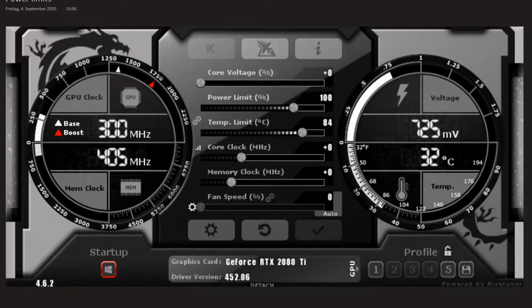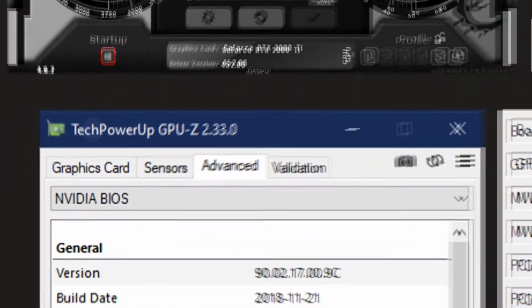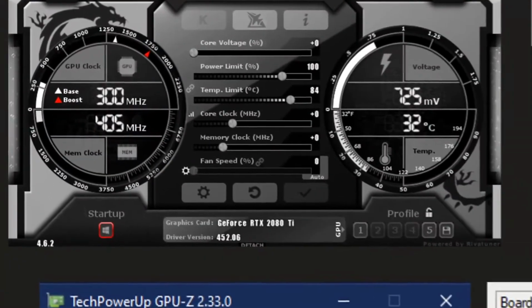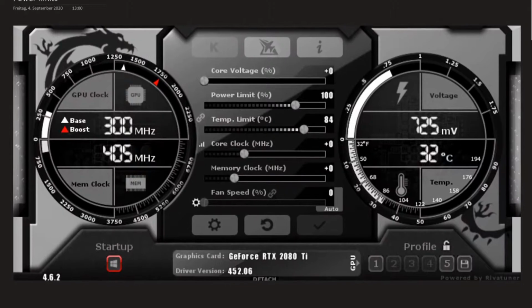If you're not running into one of those other walls, like if you have an OEM card that's running really hot, you're probably going to hit a temperature limit. But most of the time, it's a power limit that you're hitting first. So raising that power limit will give you performance for free, basically. Raising the power limit is one of the easiest, a bit more advanced overclocking techniques, because you can just max the slider as a beginner and then you're set.